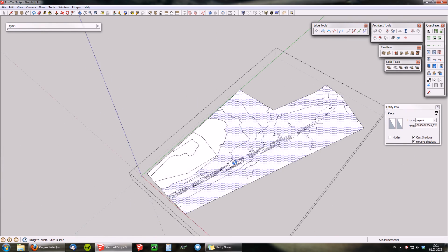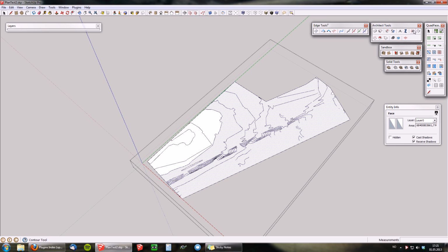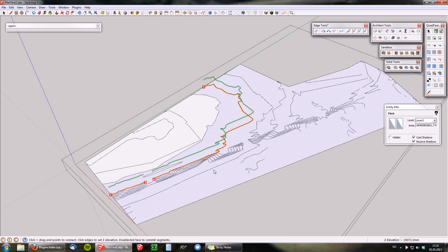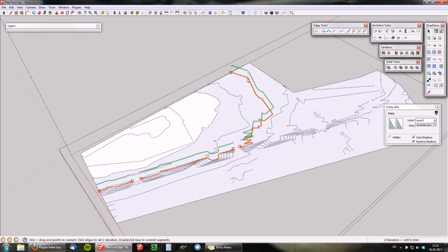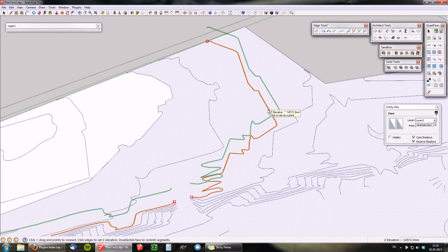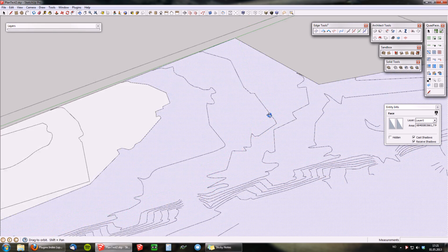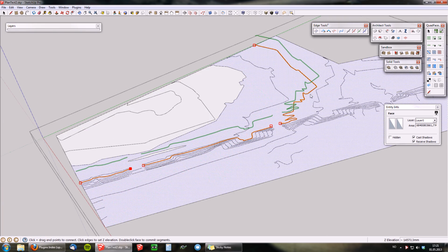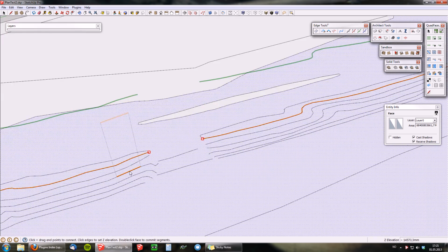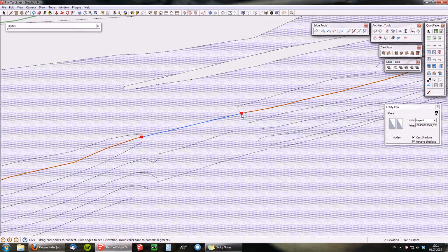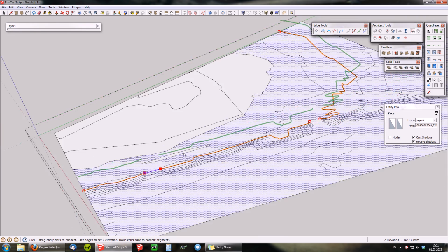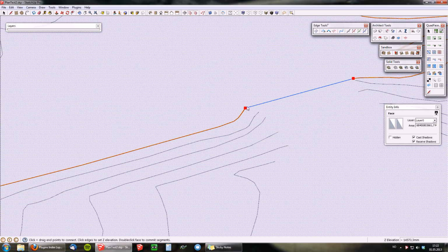And I got these contour tools, and what it does is I select one of the edges on this face, and it finds the edges which I still have above. It highlights every edge matching from the same elevation, so I can tell on the same elevation this one needs to be connected, and this is the most obvious suspect. And this one, click and drag, snap,